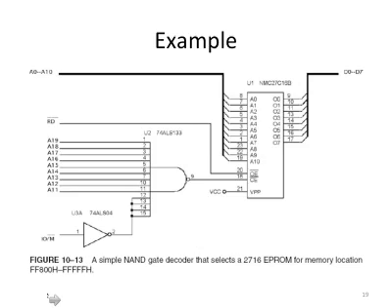So what's happening here is all the inputs of this NAND gate are ones, so you have a 0 as the output. So you have 0 to the chip enable. You also have a 0 to the output enable, and you have the valid addresses for the lower 11 bits. So this EEPROM will work, and it will output data.